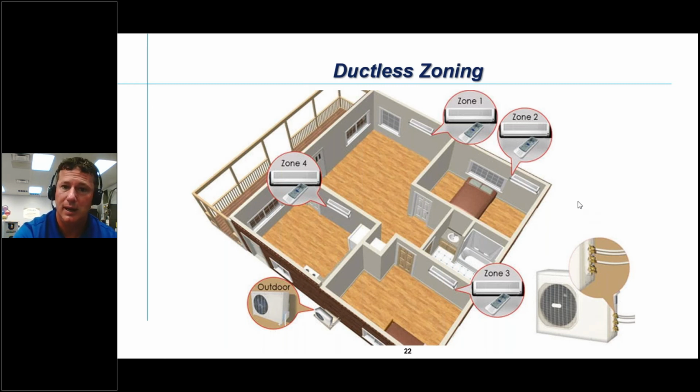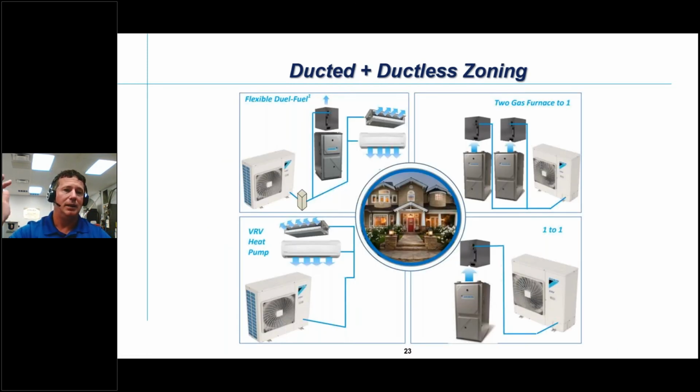Well, now we're moving into the VRV Life system as well, which is basically the same as a VRV 4S that has been converted to single phase operation to work in residential applications. So now we're talking about still a communicating system, but on a slightly different platform, because now we're going to be able to use, if we look at that top left one, an electronic expansion valve cased coil on that Life system.